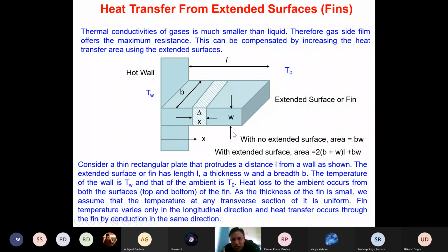And when x equals L, when I am taking this particular element, my heat transfer is taking place only along the circumferential direction, isn't it? But when I reach this particular end, this additional edge becomes available to me for heat dissipation. Do you all agree? When I reach this end, this is the additional edge I have for dissipation, in terms of the shell balance, correct? Yes, sir.